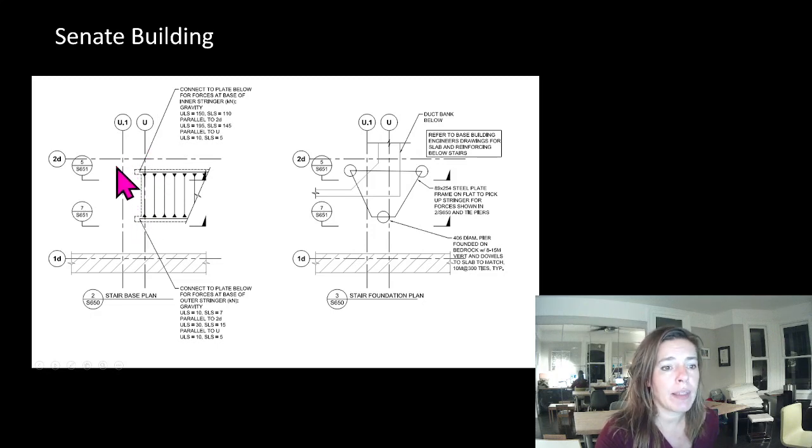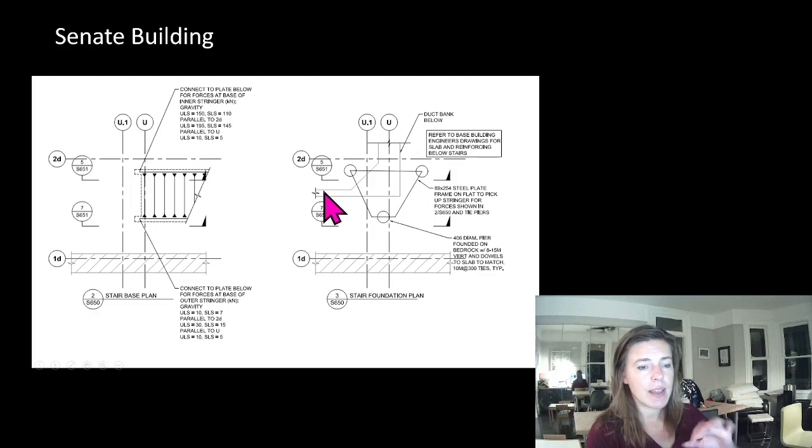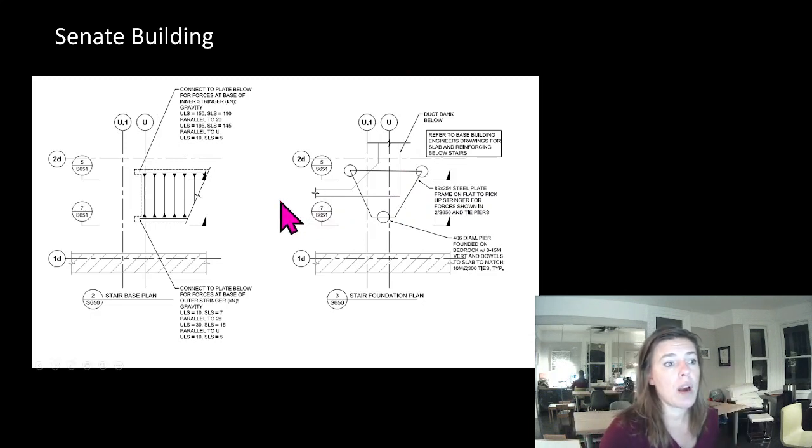Normally I probably would have put a footing there and dealt with it. We had two problems. We were on existing substrate, so they were already at it. There was an old building there, so the foundations already had to go down very deep for anything new they were doing. They had already tendered those, and they were putting a duct here. So they had a duct that was then being encased in concrete for I think it was all the fiber optic stuff. There might have been a power line in there as well of some sort.